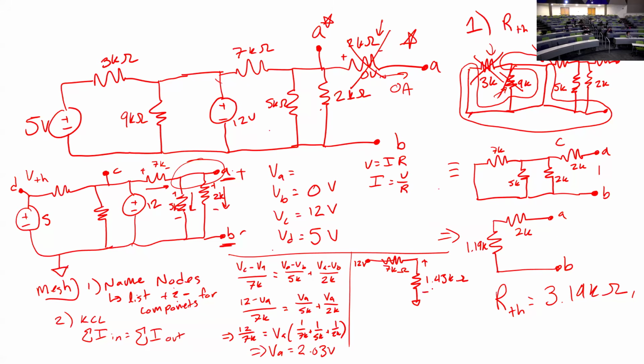So I'm looking for my voltage here, and that voltage is 1.43 over my equivalent resistance, 8.43, times 12. And that, thankfully, gives me 2.036, but that's just a rounding error, volts. Okay? Two methods gave me the same voltage. Both will be right. It's whatever you see that makes your life easy.